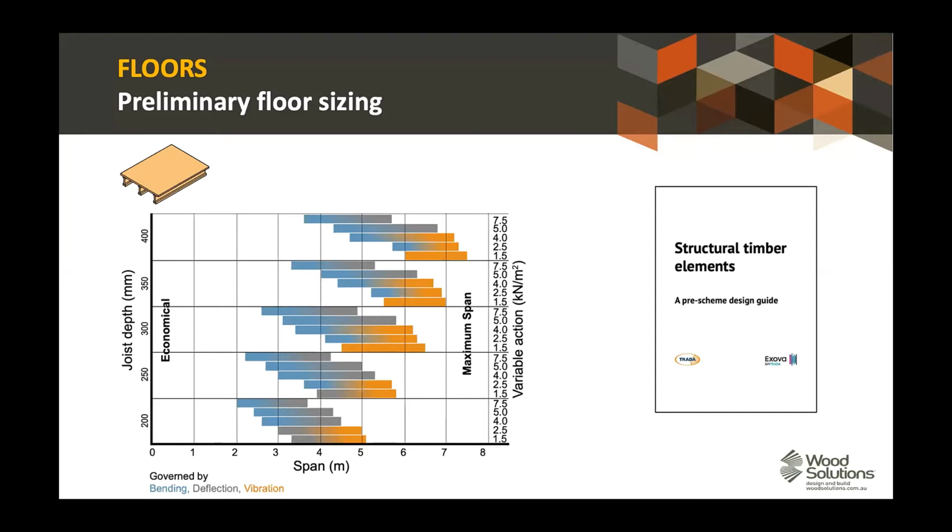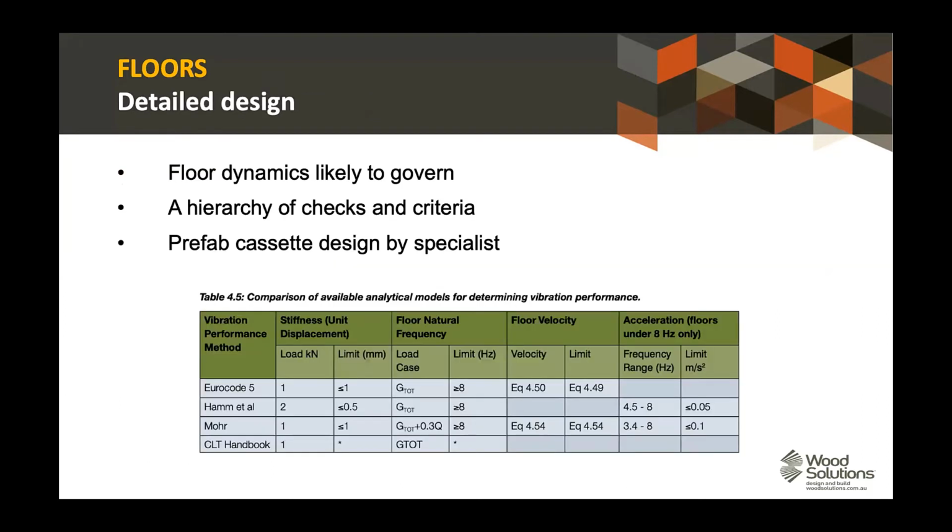And you can see that for what we might consider efficient structures, our floors will be governed by dynamic performance. So I've said here floor dynamics likely to govern. Actually, if I was doing scheme design on a reasonably spanning floor that I was trying to make as efficient as possible for a mid-rise building, my first check would probably be a dynamics check. And within that dynamics check, there's a hierarchy of checks that you can do.